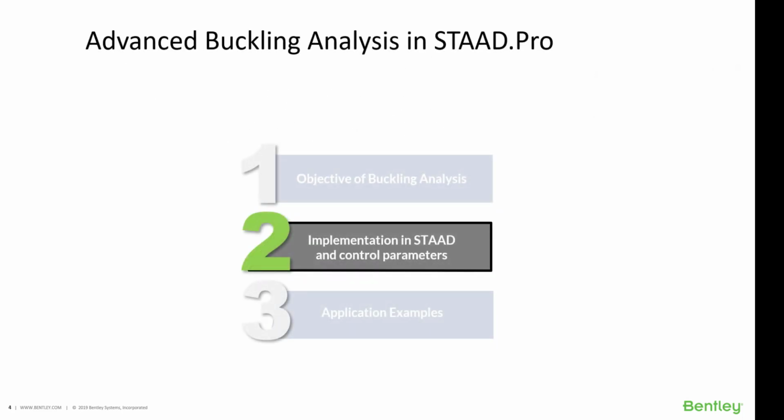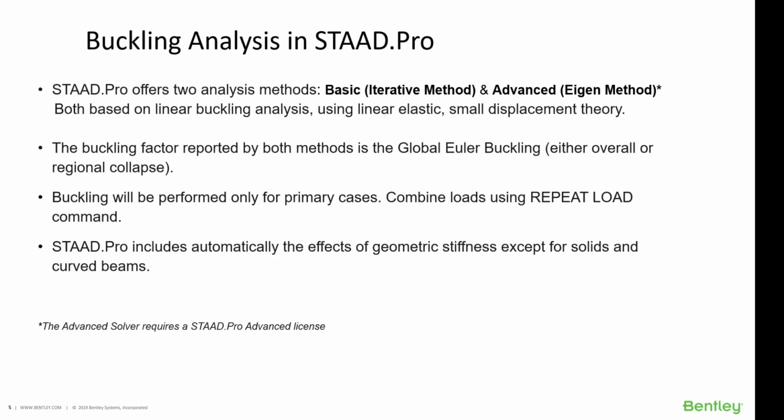Let's have a closer look at buckling analysis implementation in STAAD.Pro. STAAD.Pro offers 2 analysis methods, basic and advanced, both based on linear buckling analysis using linear elastic small displacement theory. The buckling load factor reported by both methods is the global Euler buckling. Buckling will be performed only for primary load cases. Combine loads using repeat load command.